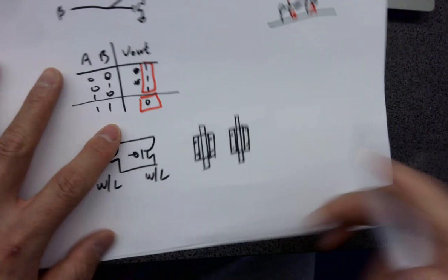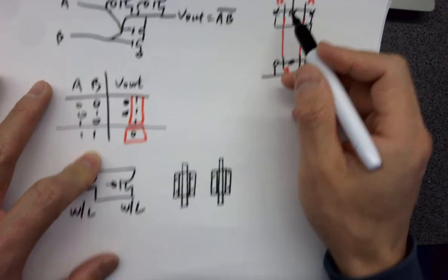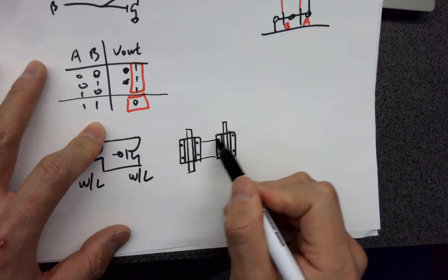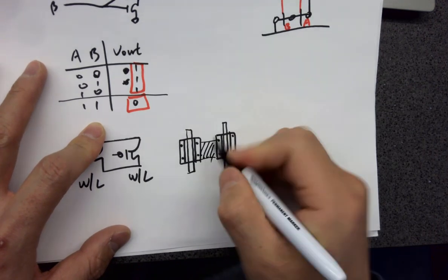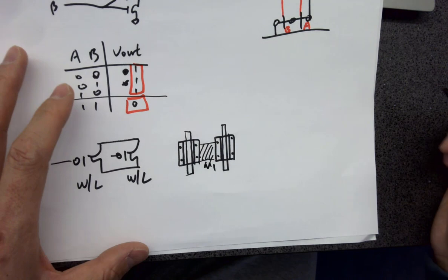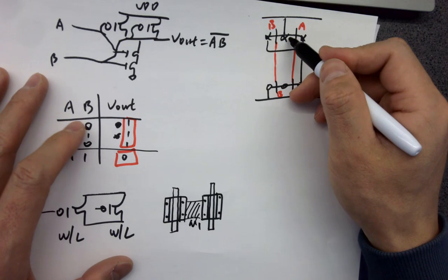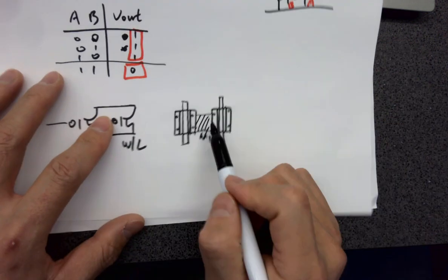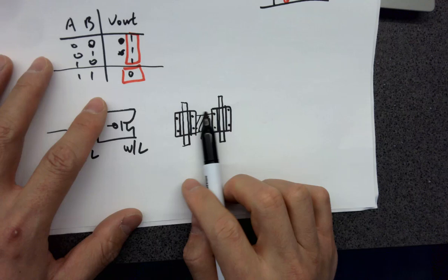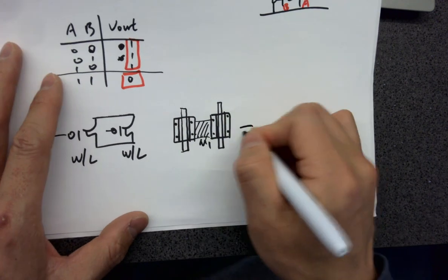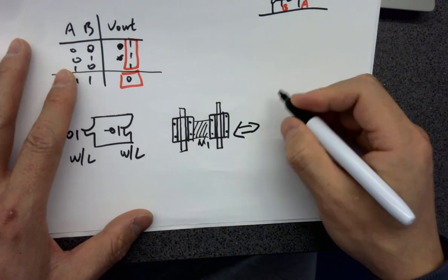If you are not merging the middle node, you need to connect the two middle nodes with metal one. This is metal one. It's just method 2. This is method 1, you merge the middle node, or you don't merge the middle node but use metal one to short them together. It's still the same thing. And this is equivalent to just one transistor.